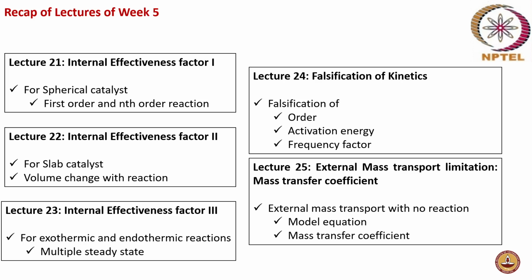As the Thiele modulus goes large, the effectiveness factor has an inverse relationship with it, and this region is more of an internal diffusion controlled reaction. In between these two regions, both the surface reaction as well as internal diffusion control the reaction.